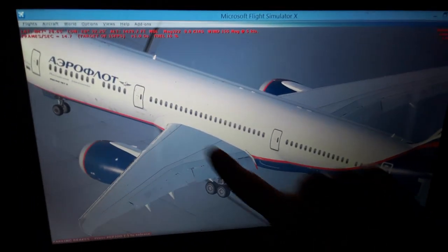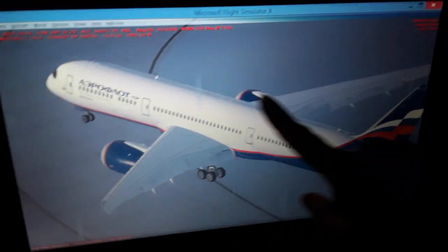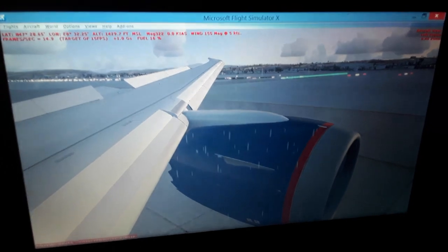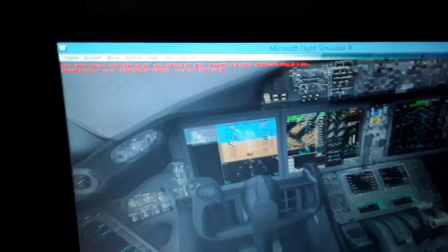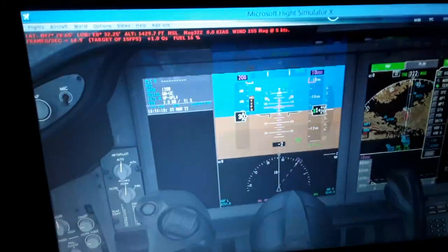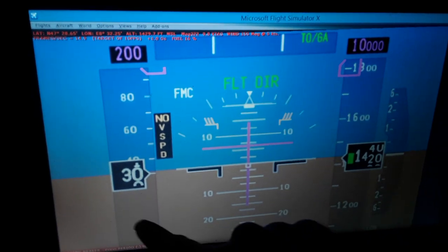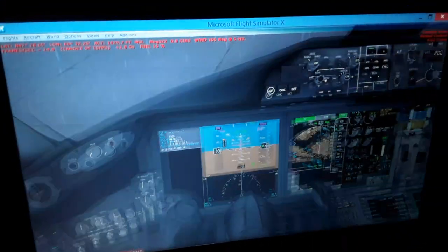The airflow becomes detached all the way back from the top surface of the wings, and we're gonna have the aircraft falling. So we need to pay attention here to monitor the stall speed all the time. In the primary flight display you can see the airspeed indicated. I'll talk to you about it now. Airspeed indicated. You have also the stall speed here below with a red and yellow indication.